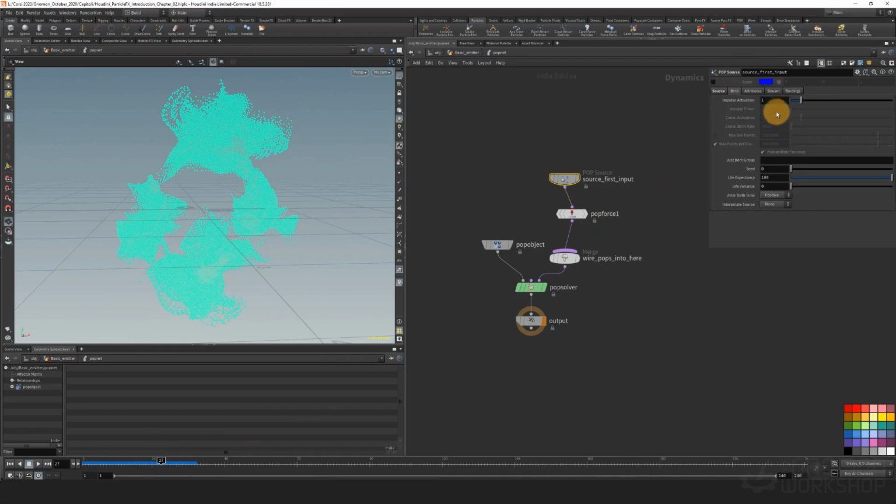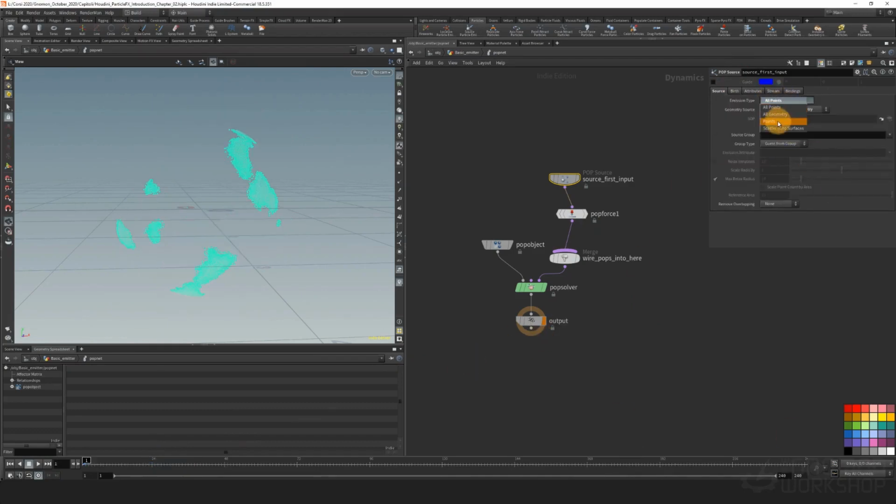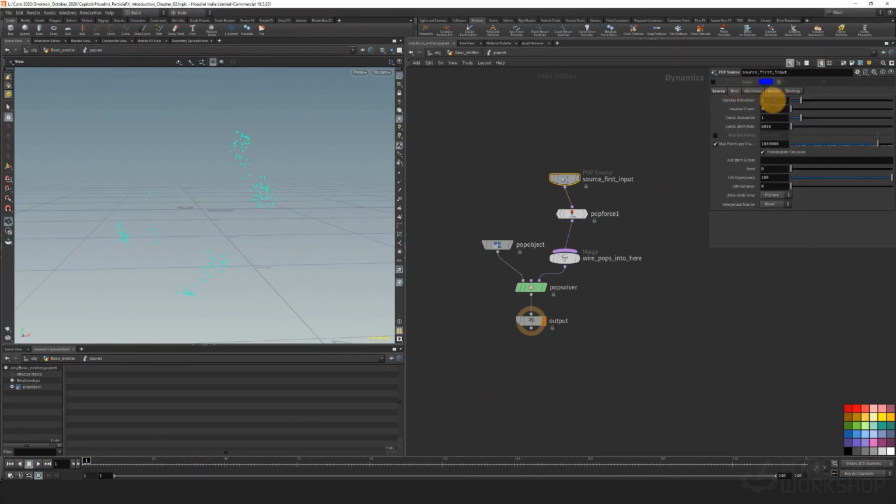Let's say about the source, we go for points, so we adjust this area to emit particles, and let's say that we have a key there, so out, and then we say that, for example, at frame 25 we still have the activation, and then at frame 26 we have no more particles.